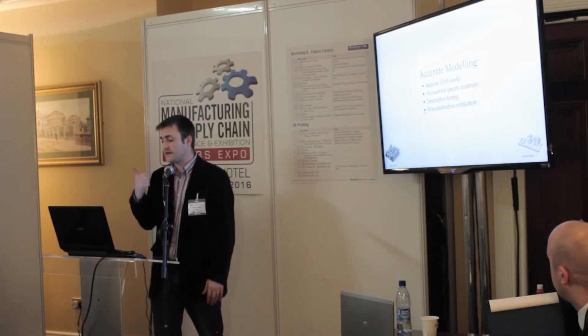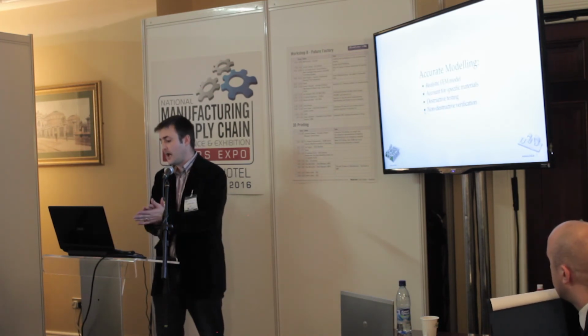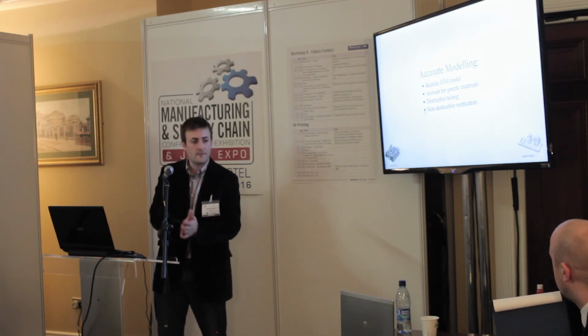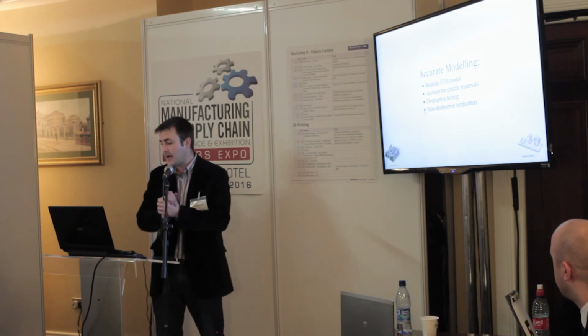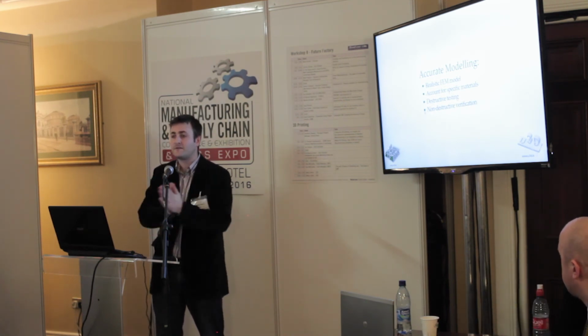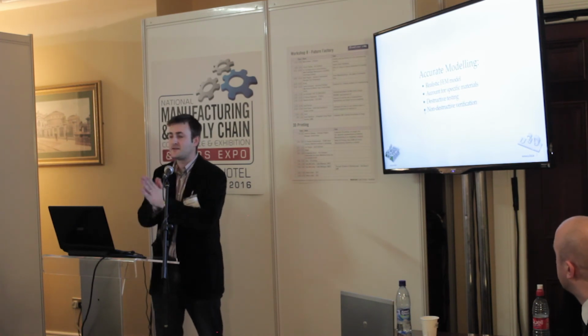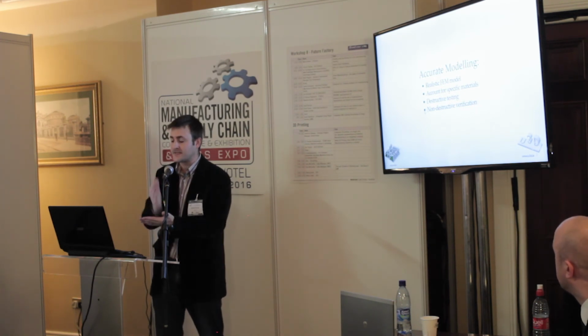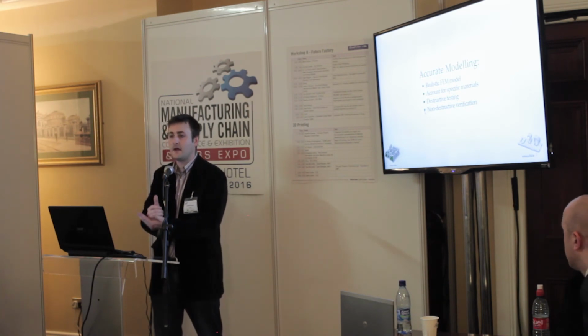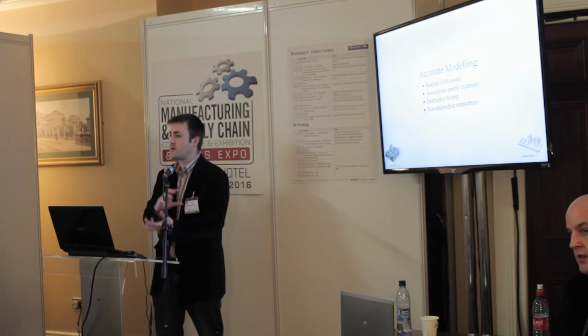So for it to work, we need realistic modeling. Another thing that we don't see between the two communities, the optimizers and the actual 3D printing community, is that they're not validating their models. You have to validate. If you design it in the computer, you have to print it, destructively test it, and verify that the two are matching up.